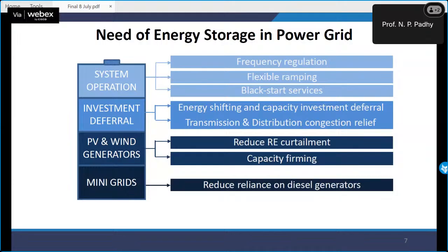Let's say this is our MNIT Jaipur academic campus. I have 0.5 megawatt of PV, and the grid is out, the 33 kV substation is out for some time. Then my 0.5 megawatt of solar panels will not give any energy, because the grid is not there. So how do I do it? If I have a battery in the campus, I can make my battery a reference bus. So the voltage of the battery can be sensed by my inverter, and hence I can start generating.